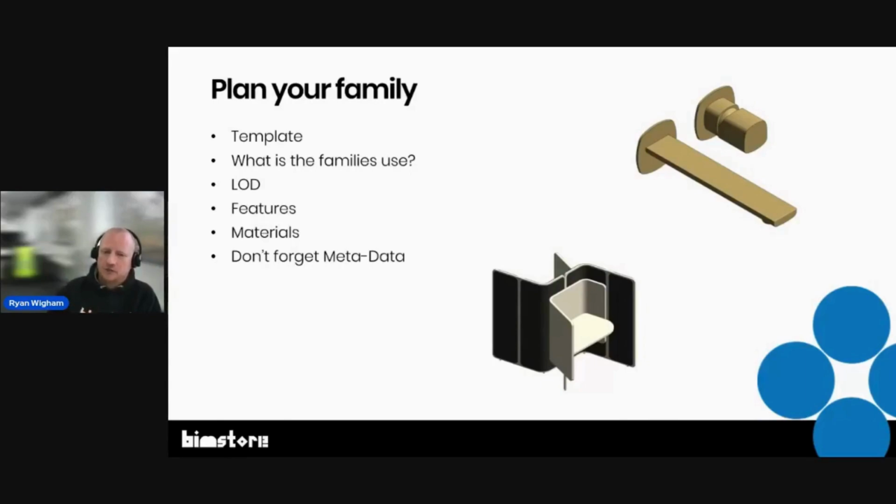If you're attaching something to a wall, face-based allows you to. It doesn't have to be a wall. You can attach it to whatever's in that project and set it to the right height. If you move it, it'll go with it. A generic one is a bit easier to place. You can just go into plan view and place it. If you build parameters into it, you can change its height. I use the default levels.